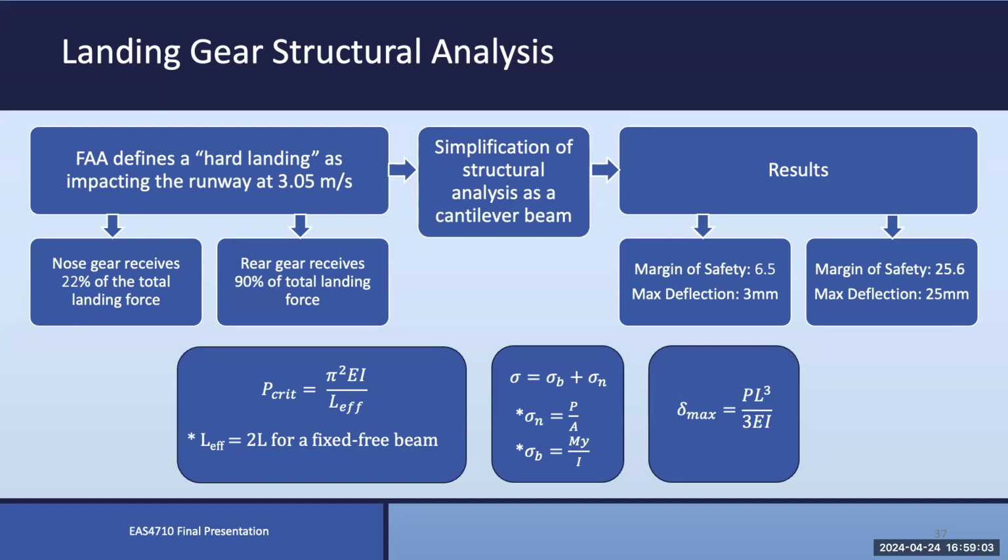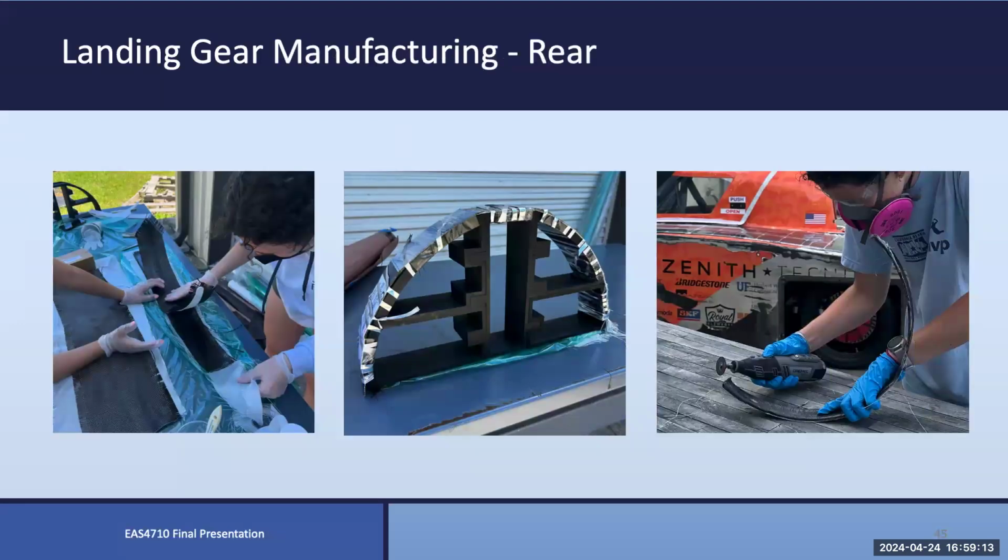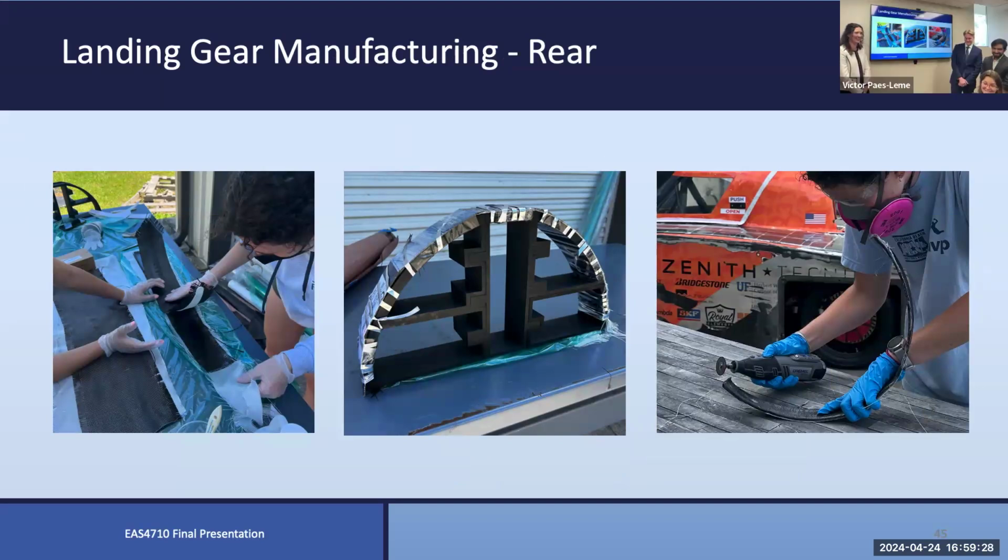The actual manufacturing, you mentioned the layup for the main landing gear was like a 45 ply and then 290 plies and then a ply of fiberglass. Correct. Was this unidirectional tape or fabric? The fiberglass? No, the carbon. I mean, the fiberglass, I have questions about the fiberglass too, but is the carbon tape or fabric?